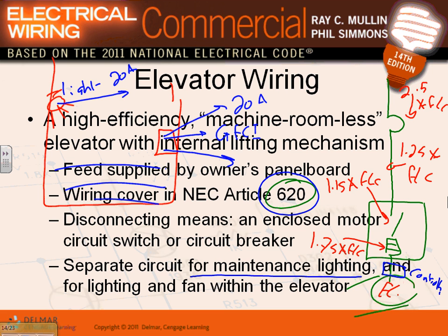Any questions, guys, about the elevator? So next project, we will have an elevator. When you size it, Rob, exactly what you said: you're going to have a circuit breaker sized, the feeder, as well as the disconnect and the fuse next to it. The controller, we don't even mess with the controller. They have their own controller, guys. We just land our cables inside the controller.